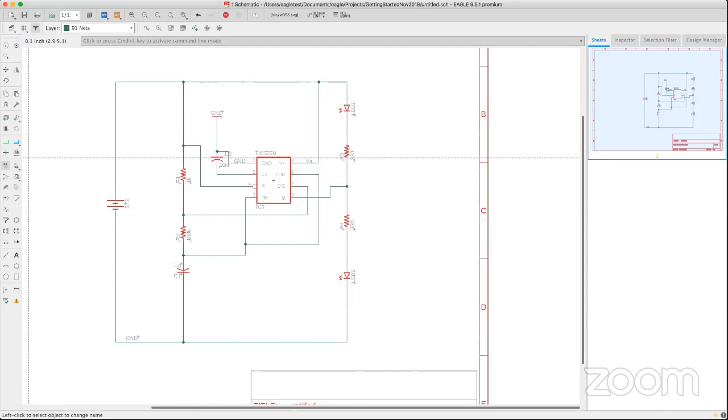What was the reason behind breaking out the pins? It's a feature that EAGLE has in case you have a component that has, let's say, hundreds of pins. Instead of having to break out each pin, especially for designs that have multiple schematic sheets, you may want to break out the pins and only have the name of the pin. That way you could have that net name assigned on a different sheet.